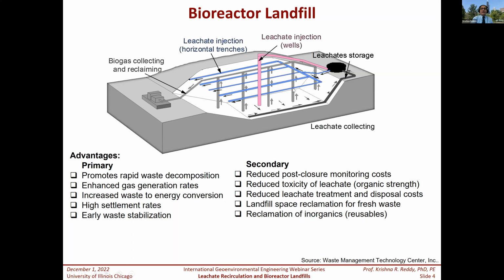Or even if you're doing this leachate recirculation during the operational periods, if you have a settlement that happens, then you can put more waste in that saved space as a result of the settlement. And at the end, if this degradation happens really fast and all the organics get converted into gas and removed, then you only have inorganics, and we can go into landfill mining and recover any usable materials out of that. So this has a lot of benefits, right?